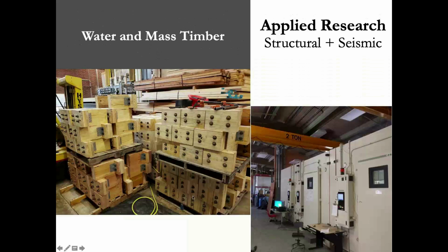Another important area is looking at the impacts or the interrelation between moisture and strength of wood connections. And we have a large project ongoing, which is looking at different kinds of moisture exposures and drying cycles on the mechanical performance of mass timber connectors, looking at various species and different kinds of connectors. We don't have results yet, but we're already learning a great deal from this work.